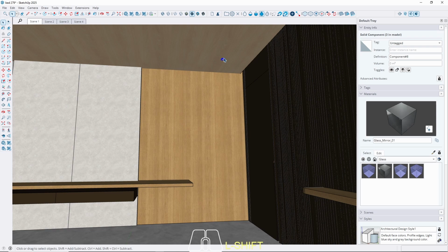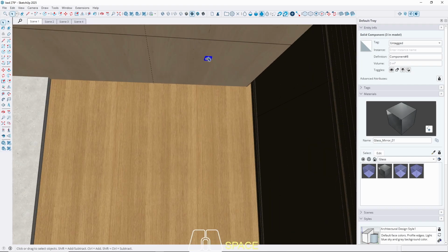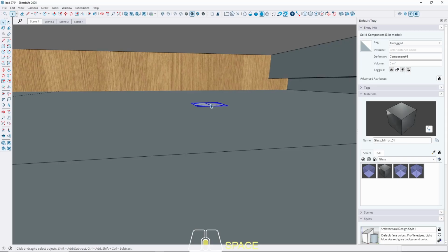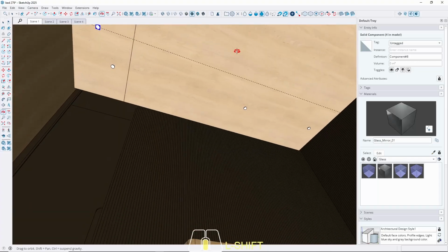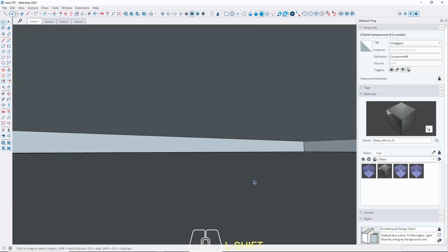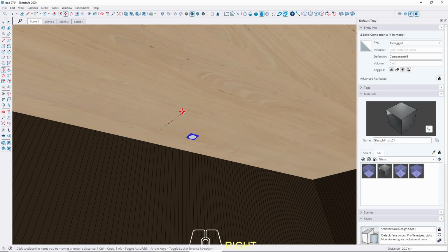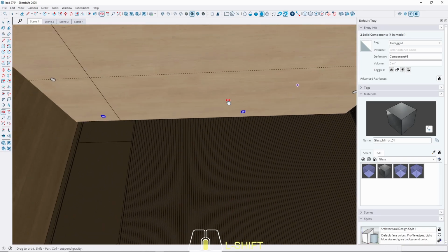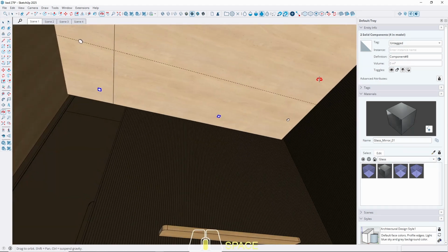And let's make a center point here. It should be right here. Let's make a center point and then mark it to here. And make a gap 30 centimeter from the panel, like this. Yeah, it should be 30. Don't make it too far, because the purpose of this lamp is for washing the wall. That's 15. No, not 15. 25. Okay.